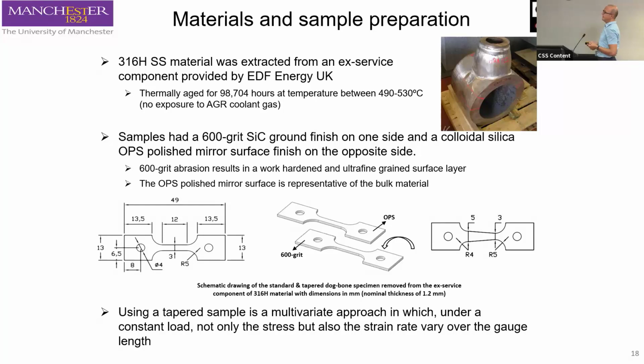And we used either flat dog bone samples or, when we wanted to identify the effect of stress on oxidation and carburization, we used a taper sample, which has the advantage that with one sample we can look at different levels of stress on one single sample.